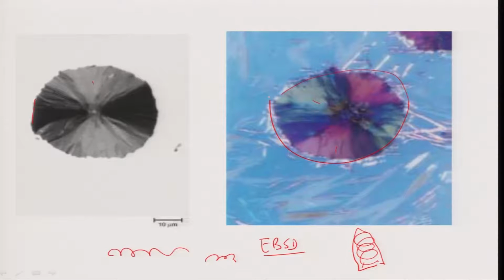the toughness requirement is high, like housings. In all these automobiles, the rear axle housing, front axle housing, and gearbox housing are made up of these spherical graphite irons, because they can absorb a lot of impact energies. When a car moves on a bumpy road, a huge impact happens, and this impact can break away these housings. So, that is why these housings are made of this casting.